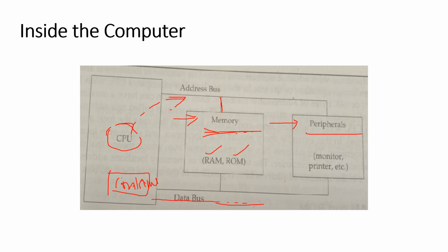Okay, let me call it a control bus, and this is the one which is going to tell whether the data on the data bus is to be read or written. That means the information is to be fetched or loaded. Now the data bus picks up the data either from or to the memory, and it comprises many data lines. Normally, the data bus size varies from 8 to 64 bits.